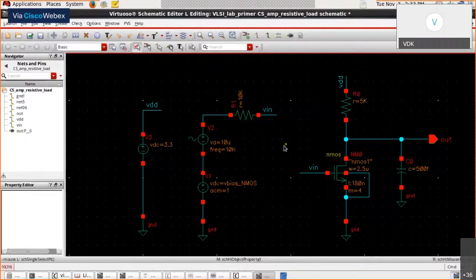It typically is listed as 600 ohms. It's a routine lab type function generator, right? So here we have the setup. We have set up the bias voltage in terms of DC voltage V1, right? It is actually defined as a parameter value, V bias and MOS, right?